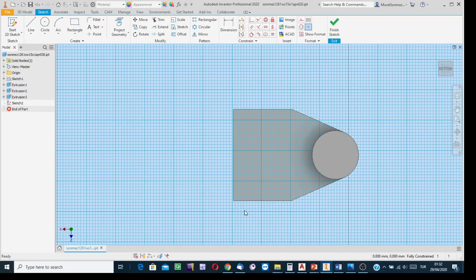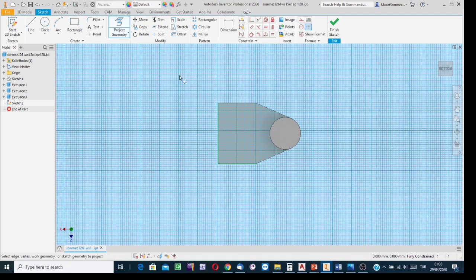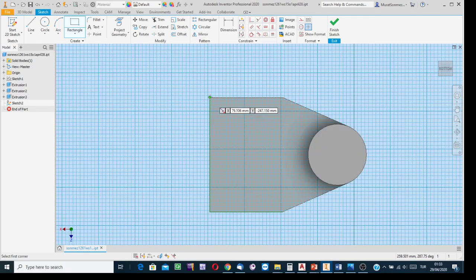Whatever the technique is, both of the cases need to apply the project geometry process, have the image of this boundary, have the projection of that boundary. And then, the terminal point of this boundary can snap the cursor. Start the rectangle creation process. Why? Because the extension to create is a rectangular prismatic extension, so its base is a rectangle. Okay. Snap this terminal point.